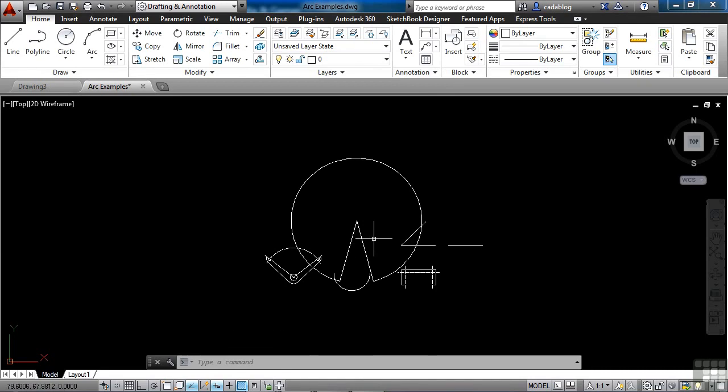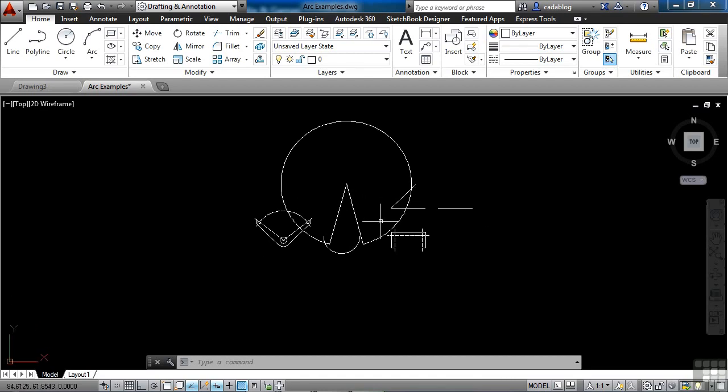This will make your first point the center point of the arc, and it will make you draw all sorts of arcs. So now you have 2 ways to draw an arc: from a start point to a point in between and then to an end point. Or now you can start at the center and get your start and finish points at that defined radius. Now, you don't always know these points. That's what's great about the arc command. The majority of what you're going to need for your arc command are the 2 that I just showed you.